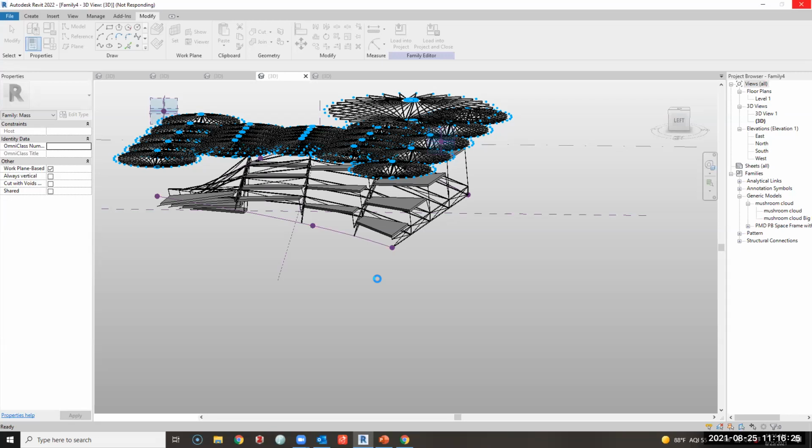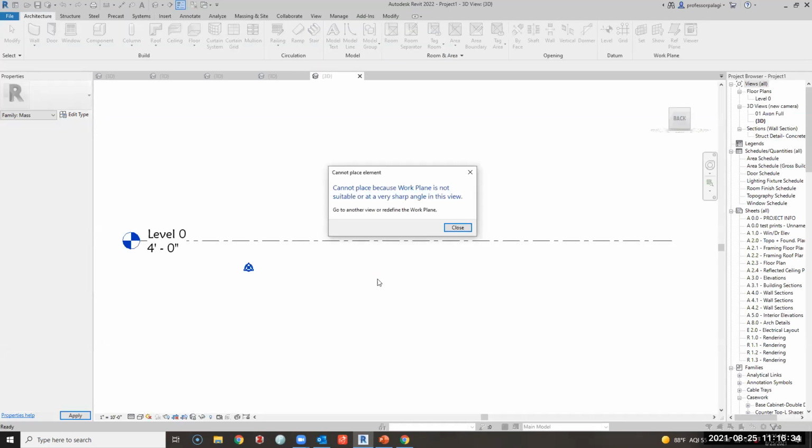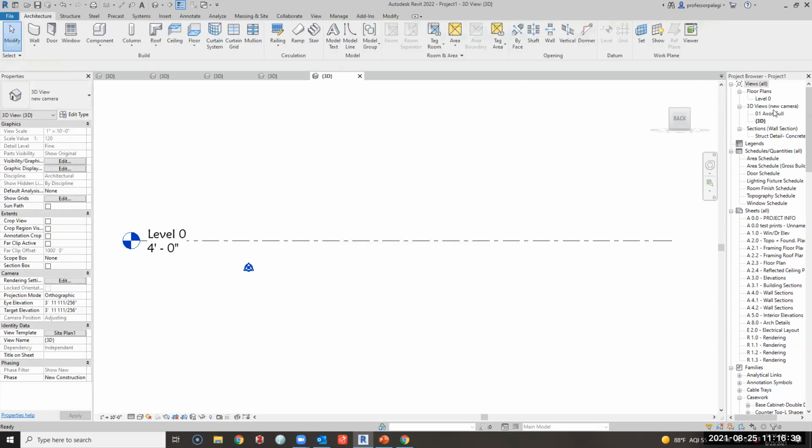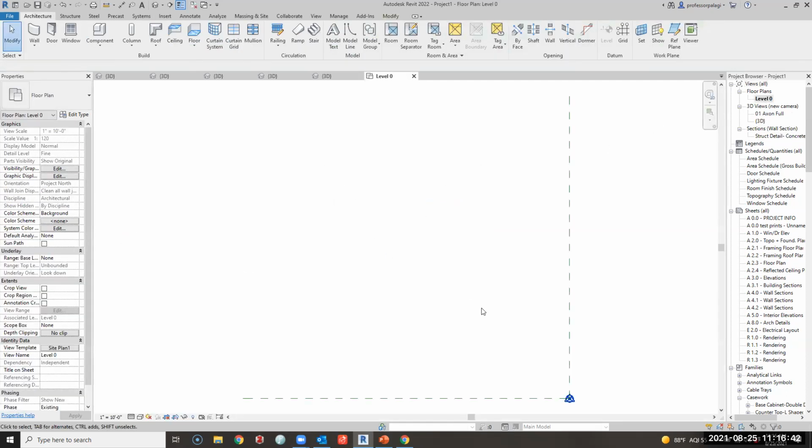We'll get to a little later where everything we do in conceptual mass you could do in the real Revit world, but you've got to do it in the in-place mass editor. It's got to be in a floor plan level. So that idea that we could have made those surfaces and divided those lines and placed all that stuff in the real Revit world too. You just got to do it through the window of in-place mass, which we'll talk about later. That's a certain thing within Revit, and that's really what the conceptual mass world is. It's just that on its own.